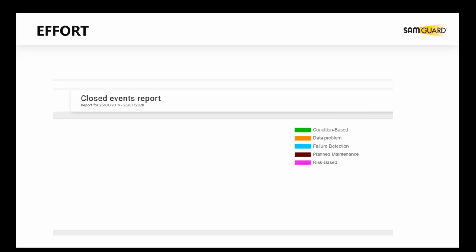Keep in mind, just to align the expectations, that not all alerts are valuable. Not all alerts will increase your productivity. For example, planned maintenance. If you do planned maintenance, of course, the data will become crazy, and will probably trigger an alert. Now, in a perfect world, of course, the software would know that there is planned maintenance and would not trigger an alert. But in reality, in most plants, not all the data is connected.